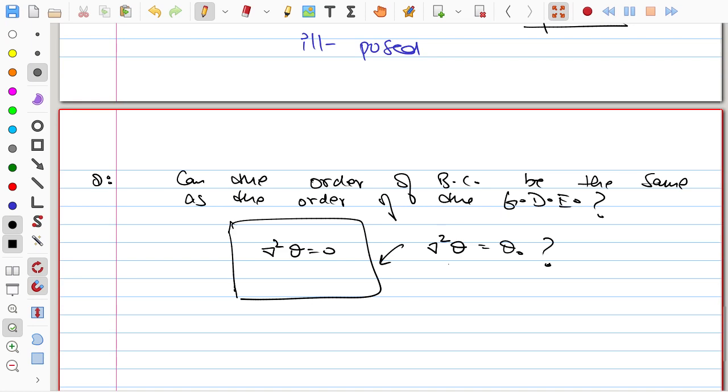Okay, the one at the back, yeah, orange shirt, yes sir. You, yeah, that's orange to me. Why? Exactly, very good. Please sit down. It's contradicting the governing differential equation. I told you governing differential equation is applicable inside the domain as well as the boundaries. So if that is the case, then I have already told you Laplacian of theta is 0. Then you cannot have Laplacian of theta equal to something which is non-zero on the boundaries. Okay? Is that clear?